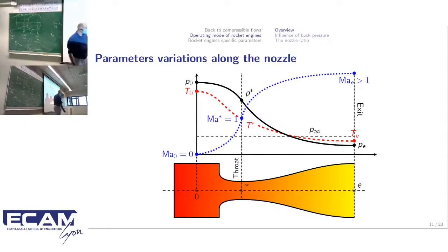For only one reason: the influence of this part on this is only possible if the speed of the flow is lower than the speed of sound. Just remember, you are swimming in a river, and you are swimming exactly at the same speed as the river. You will stay at the same position. And if the speed of the river is higher than your own speed, you will just get pushed back, even if you are swimming. It's exactly the situation here.